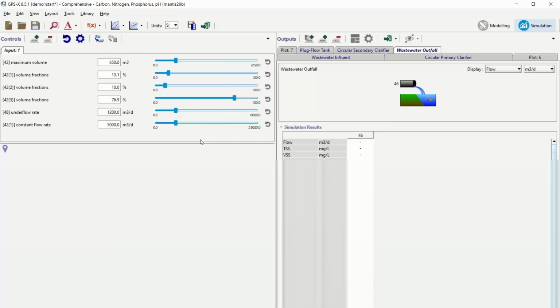Now, the way that I find this useful is sometimes in these more complex layouts, you have to go in and set a bunch of pump settings and connection points and flow splitting and whatever. After I've got it done, I'll do one run of steady state and then plot the Sankey diagram just to make sure that these numbers are what I intended them to be, and that I didn't accidentally flip a splitter around the wrong way or activate the wrong pump or something like that. So these flows are basically the flows associated with each line. And there's also this little coloring here. The thicker the coloring, the bigger the number. So you can just double check, yeah, I got the right amount of flow coming to my digester, for example.